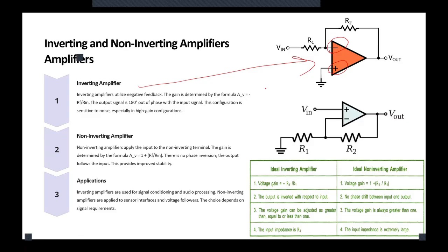We are gonna have a feedback resistor. Do you remember why? Because we want to control that high gain. In open loop, we have a high gain without any control. But with this feedback, we can control the gain. We are gonna have feedback resistors. This R2 we call RF, and this R1 we call Rin.